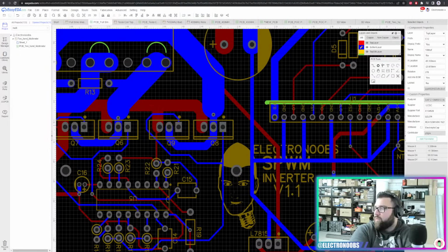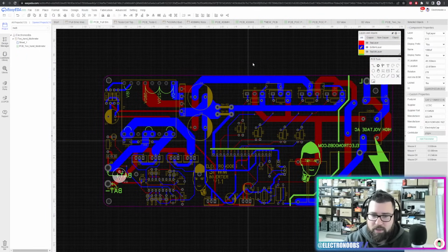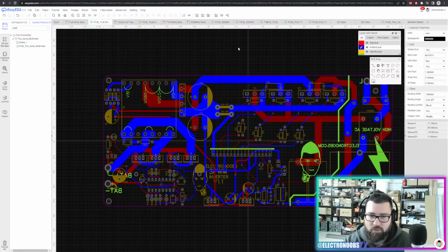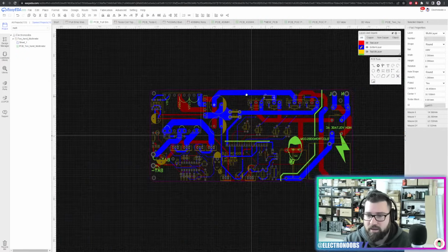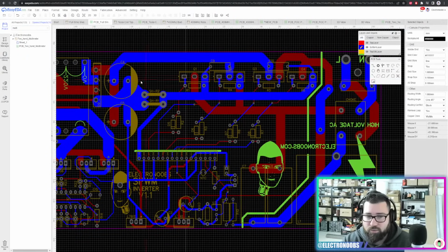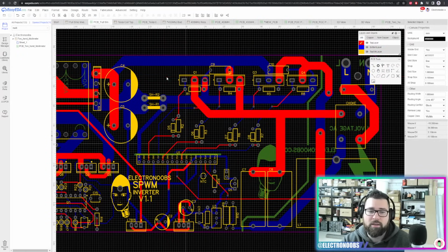How do you choose on which side of the PCB to lay the traces and the vias? That depends. For me it's not important. What is important for me is the track thickness and to reach the point where I want to go. So for example, if I want to go from here to here, I will make the track as short as possible, and each time that I have to change to the other side, I will change just to pass some other tracks that I have in the way.